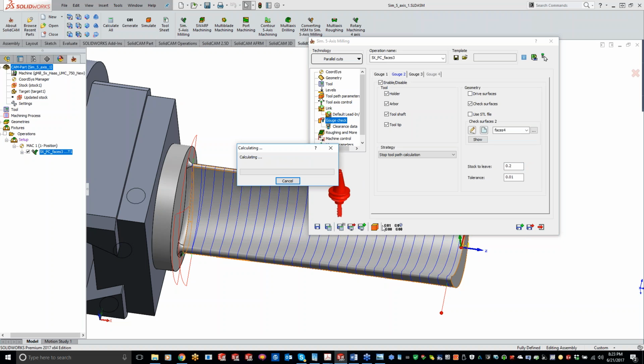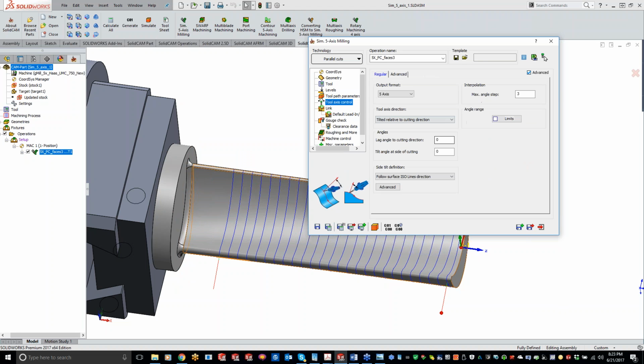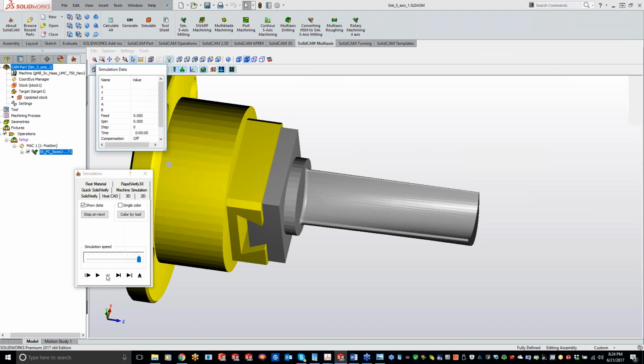Oh shoot, I forgot to kick that cutter over to 20 degrees lead. So now we're coming in there, and you'll see our toolpath isn't getting as close anymore. So let's go ahead and go to our lead angle right here, and let's just do another 20. And we should see pretty close to the same toolpath here, but now we're going to be working on the side of that ball versus the flat of that surface. So let's just see what we have so far here.